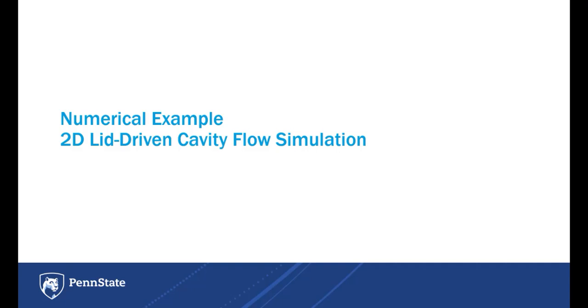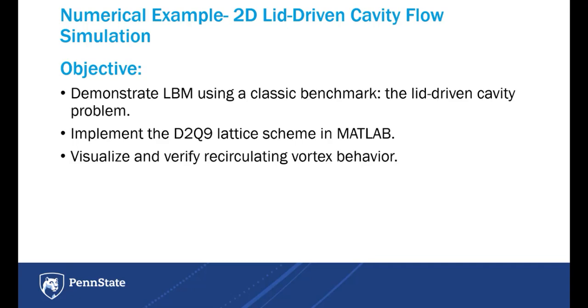Hello everyone. Today I'll walk you through our numerical simulation example, which is a well-known benchmark, the lid-driven cavity flow, using LBM in MATLAB. We'll cover the setup, the code, and the results. Our goal here is to validate the LBM approach using a well-known benchmark, which is the lid-driven cavity flow. We'll be using the D2Q9 lattice scheme in MATLAB and observe if it captures the characteristic vortex inside the cavity.